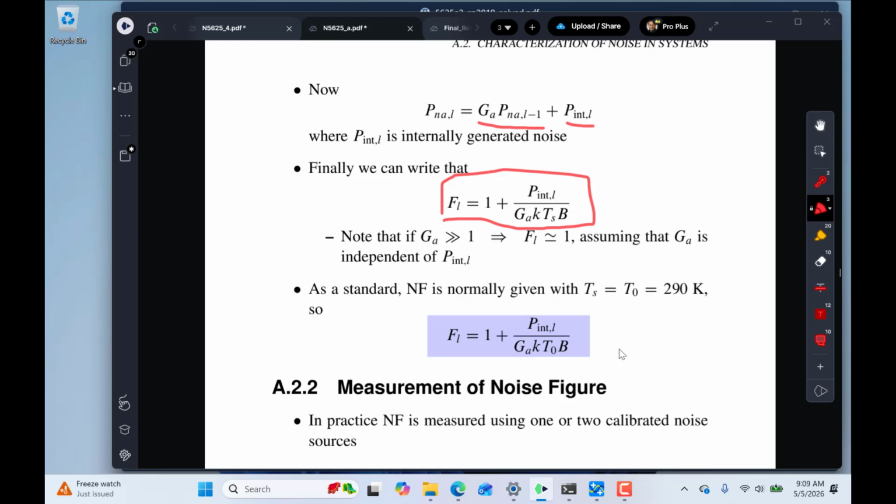Now, when I was in school, or reading specs and requirements, what would happen if the customer said the noise figure was a really tiny value, but it had to operate at a really, really cold temperature? That would be kind of not telling you the whole story. Most everybody's going to want to use it at room temperature, so they could make the component look better than it would in practice by rating it at some really cold temperature.